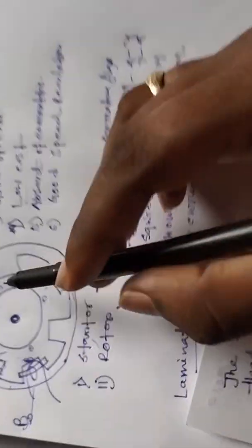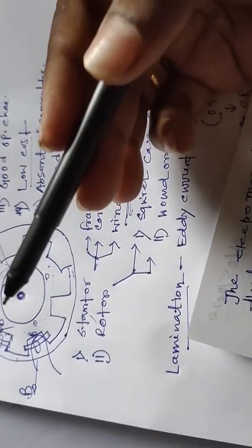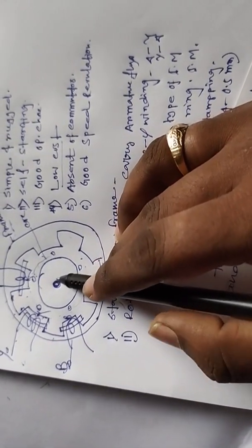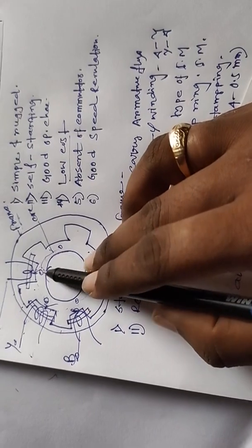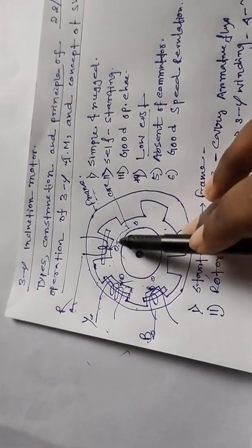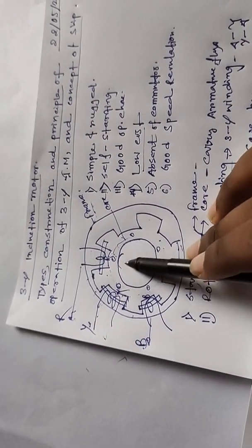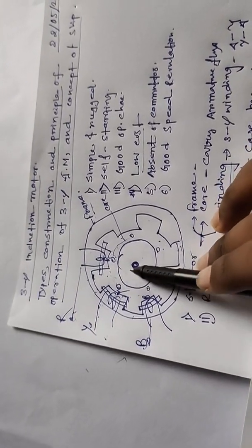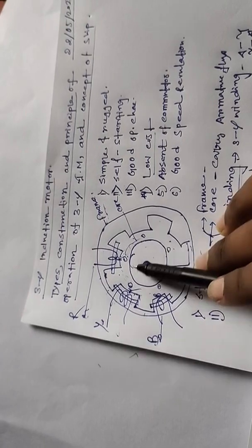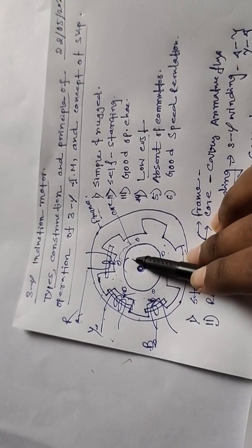Here in the core there is a rotating magnetic flux, and the rotor rotates, so a relative motion is produced. This relative motion causes the rotor emf. Here there is the rotating magnetic field, and here is the rotor flux. As the rotor rotates, this flux also rotates, and the rotor flux direction and the rotating flux direction are the same, clockwise. So there is a relative motion, but